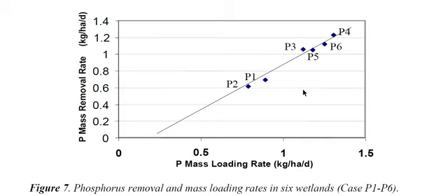So the wetland is not very good for BOD removal. The BOD removal is much better to do somewhere where you can supply oxygen on demand. The wetland does not do that. So if you remove the organics and also a large part of the nitrogen before the wetland, it becomes much more efficient at removing phosphorus. You don't fill up all the space in the soil with biofilms growing on organics. So that way the phosphorus can much more easily penetrate to sand, for instance, and get immobilized there, just absorbed. So that's the main reason why these cases work so much better.